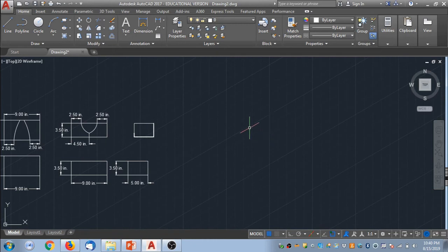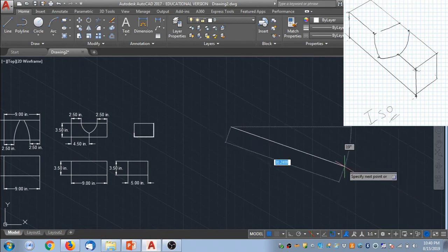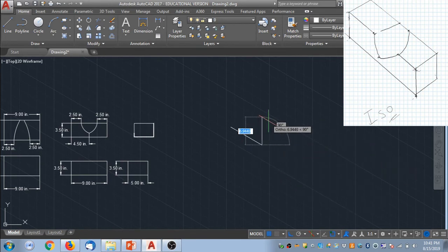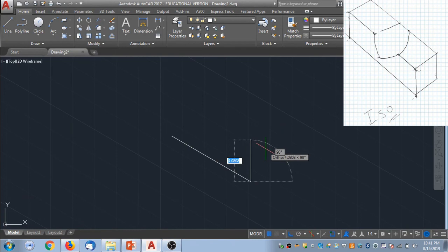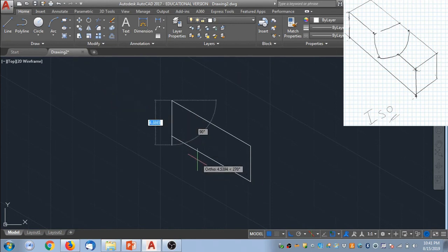And when you click on it, the crosshairs turn sideways in an isometric view, and you'll see that the grid that's in the background has shifted to a 45-degree angle. Now you saw me swipe through the cursor directions there. That is done by hitting F5, and it allows you to change which plane you're theoretically drawing in. Otherwise, drawing works exactly the same. You just need to make sure that you're in the plane you want to be in and in orthographic mode, and basically you'll just click around in that skewed angle.